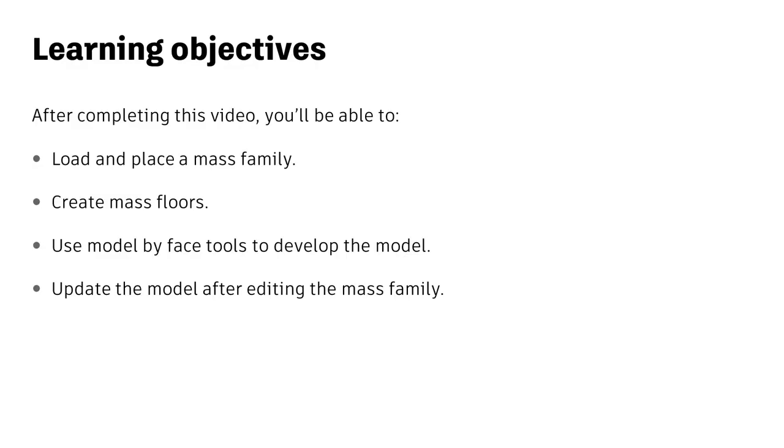In this video, we'll show how to load a mass family and place it in a project. We'll see how to create mass floors from levels within the project. We'll show how the Model by Face tools work to develop a more detailed model, and we'll also see how to update the model after the mass family has been edited.